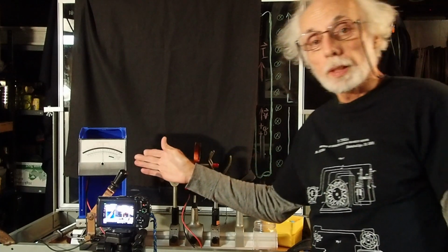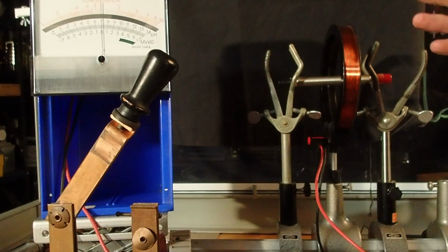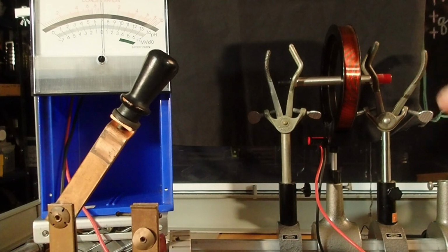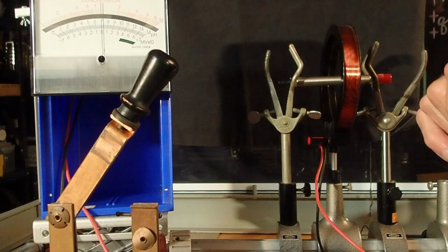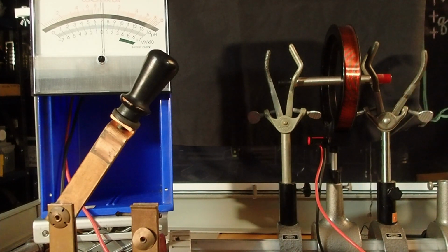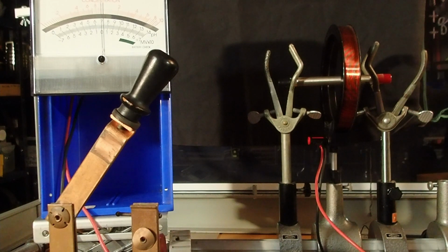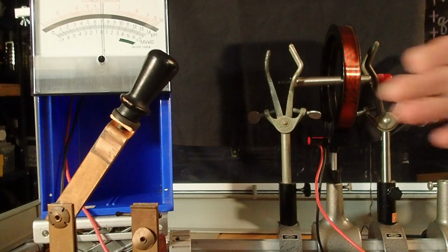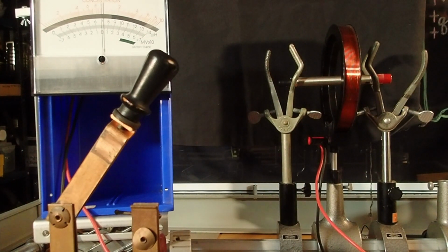We have a meter that measures millionths of an amp, a microammeter, and to protect that meter, standard practice is that you don't turn the meter on until everything's ready. You can monitor the meter, and you try to make sure you come in with the lowest amount of strength possible in case this thing produces enough power to damage the meter. So we've carefully included a switch here, so there's no expectation of electricity flowing until we move this lever.